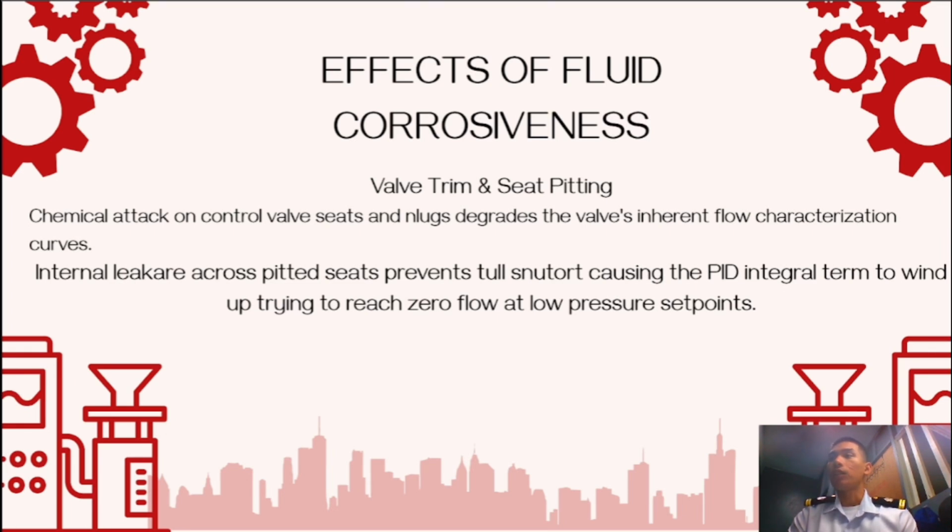Chemical degradation on final control elements: attack on valve plugs and seats alters the flow characteristic. Internal leakage past damaged seats prevents proper shutoff, causing integral windup in the PID controller as it relentlessly attempts to eliminate residual pressure flow at low set points.